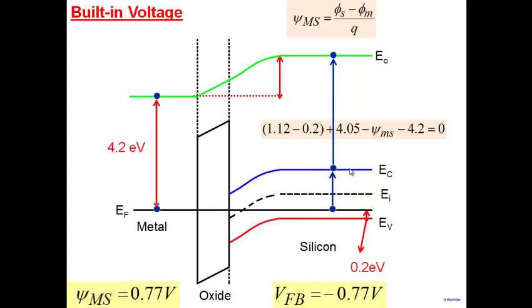It's a p-type semiconductor. As we approached the interface here, we saw that the semiconductor was becoming intrinsic here and then becoming n-type here. And from a diagram like this we could also obtain the built-in voltage between the metal and the semiconductor. One can see here that the vacuum level, E naught, goes down and comes here. So a difference in vacuum level here and here denotes the presence of a voltage between these two places.